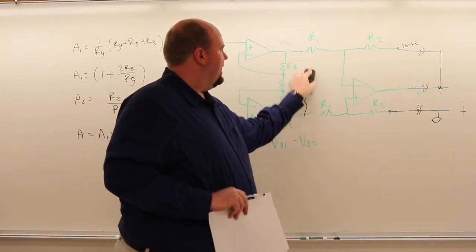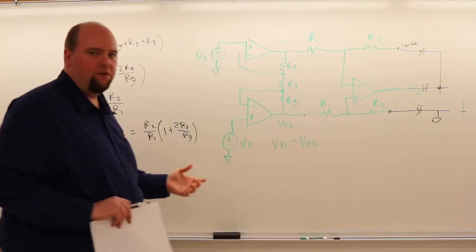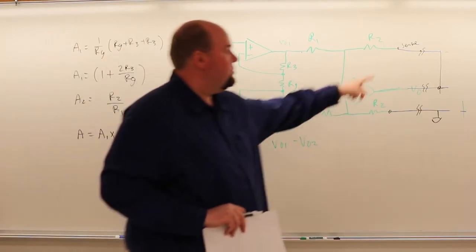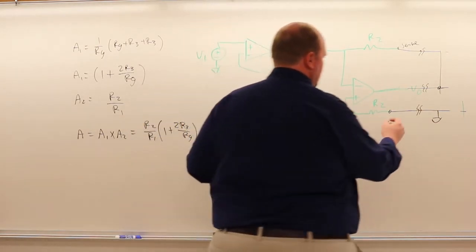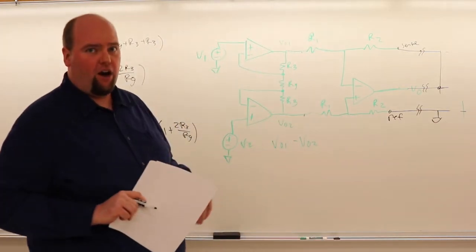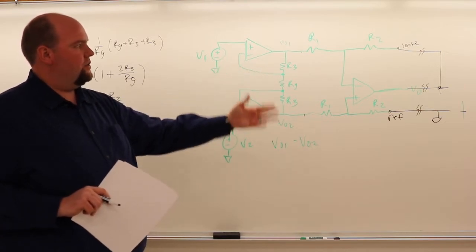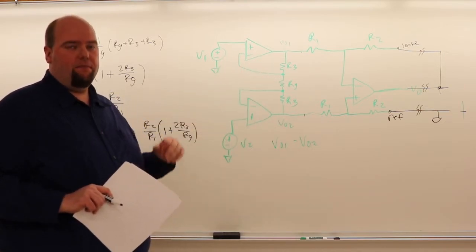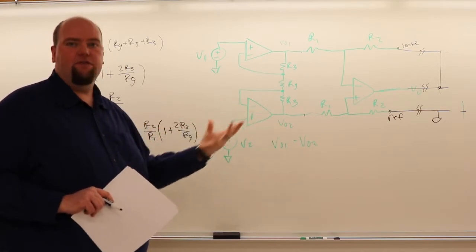If you buy an instrumentation amplifier, and you see some of these features on here, if you see a sense pin, this is typically called a ref pin, I didn't label it. And actually we'll talk a little bit later about offsets as well. If you see some of these like guard or sense, reference, if you see these on the package, note that that instrumentation amplifier is capable of doing these different things.